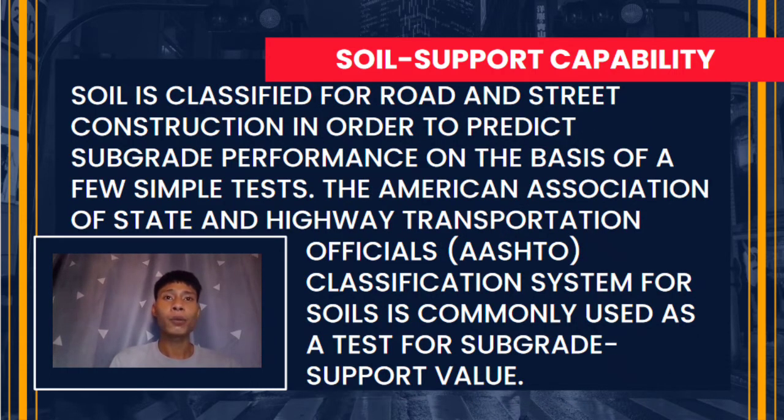Next, soil is classified for road and street construction in order to predict subgrade performance, on the basis of a few sample tests. The American Association of State Highway and Transportation Officials, the AASHTO classification system for soil, is commonly used as a test for subgrade support value.